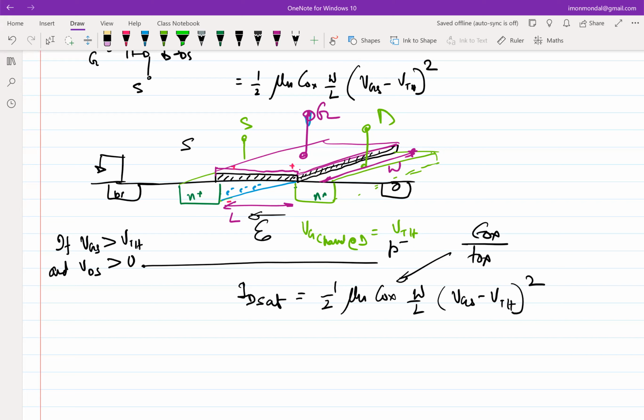However, when you are designing an integrated circuit, the design flow allows you to change W's and L's. So essentially, one time during design, you can decide what will be the W of a transistor, what will be the L of a transistor. But once you fix that, you cannot change it. So it's a one-time offer essentially.